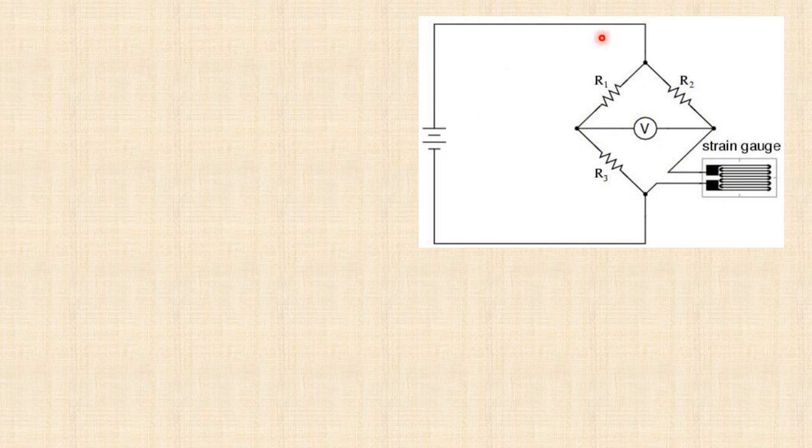Students, you recognize this as Wheatstone bridge network. So there are 4 resistors in this network. You see, in place of the 4th resistor, we place this strain gauge. Now as an example of active sensor, we already discussed this. And now active sensors always require an excitation signal. So this current passing through this network is the excitation signal. Now this strain gauge is applied to the specimen whose strain is to be measured.